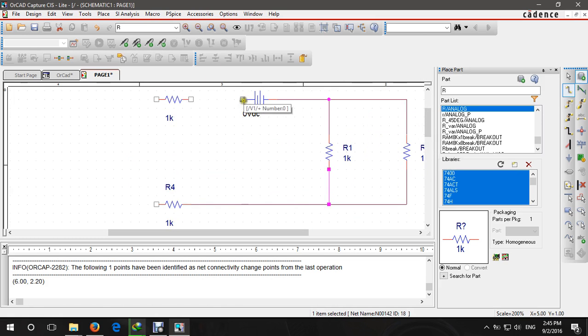Let's connect these two, brilliant. Let's just have that go there, and as you can see, I can't really, because I want my wire to follow the cursor. This is how I want my wire to go, here, down here, and then there. Now if we press the wire tool and then we try that, it's not going to happen, but what we can do is just simply do that, and that. So we click at different points and it keeps the wire tool selected.